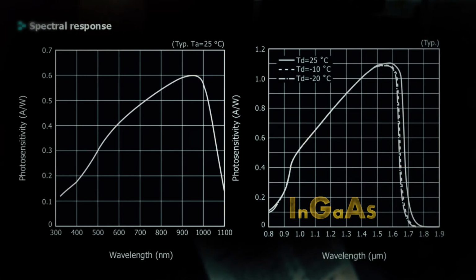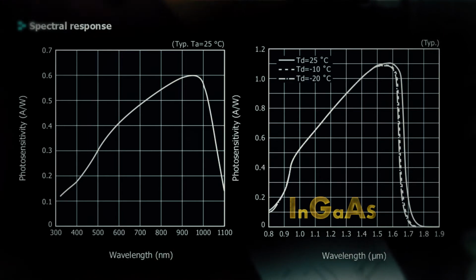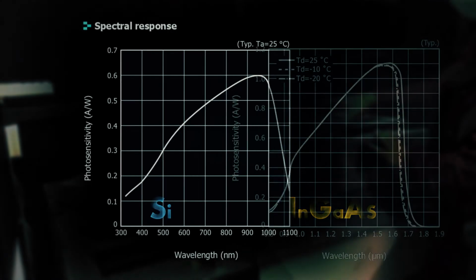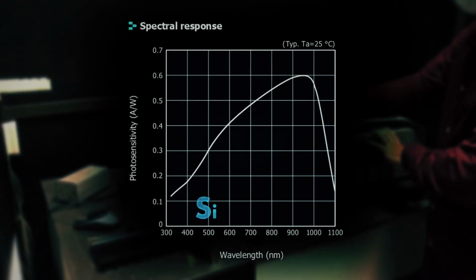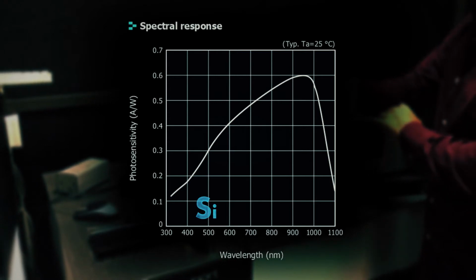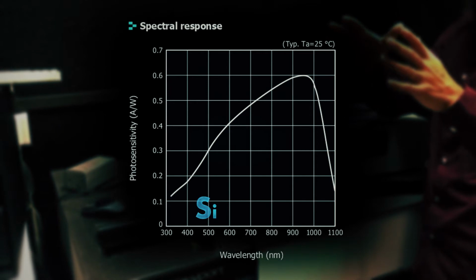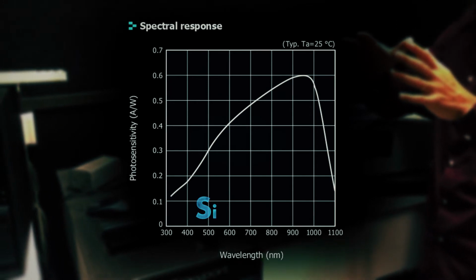The type of photodetector has an influence on the responsivity measured. In the example studied in this video, a homojunction photodetector, both the N and P sides are made of the same material, silicon, that present similar energy gaps. Doping in silicon has almost no effect on the energy gap. This provides a responsivity graph like the one seen on the datasheet.